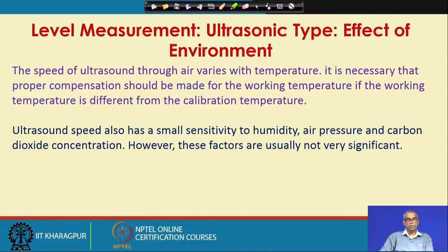So, if you take the device to different places, the different environment will have different humidity, different air pressure, different carbon dioxide concentration. Even at the same location on different days, there may be changes in humidity, air pressure and carbon dioxide concentration, and velocity of ultrasound has a dependence on these.